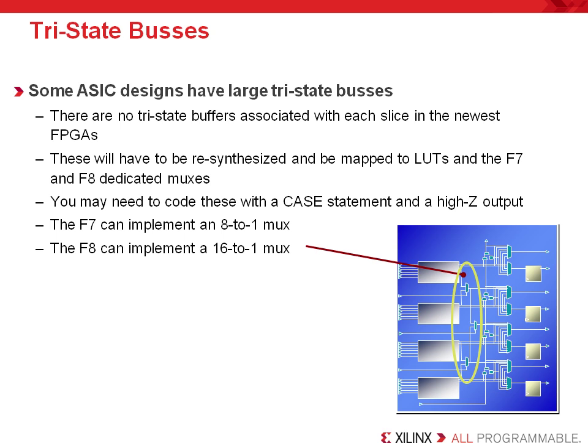Most designers infer a tri-state buffer by testing for the enable signal to be asserted, and if it's not, a high Z output is defined. Most synthesis tools will infer a tri-state buffer in this case. The problem is that the dedicated mux was primarily built to make muxes, not bidirectional buses. Historically, a case statement is usually required to infer the dedicated muxes, and sometimes a synthesis switch is required, which is usually on by default, however. So just keep in mind that you may have to convert your code to use a case statement, and this may depend on your synthesis tool.